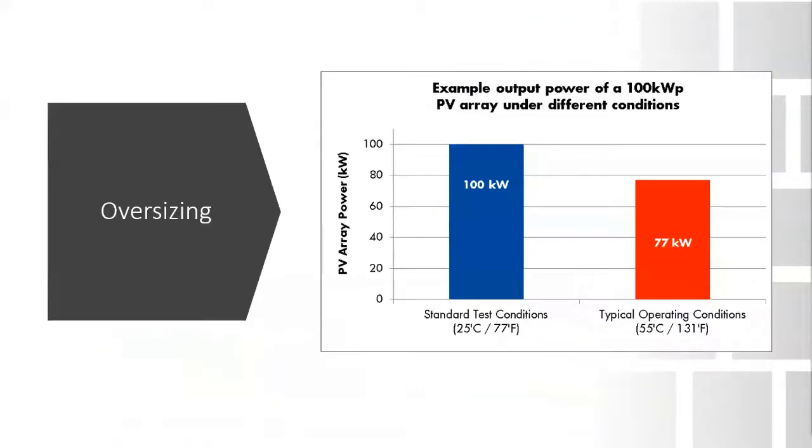When homeowners are putting solar on their home, they're doing it because they want to make a return on that investment primarily. So keeping installation costs down is key. The other thing I want to touch on, because that slide only referenced AC inverted backfed power, I want you to keep in mind there is something known as oversizing. So I can have more DC, so modules on my roof or ground, than I can have AC inverted that's backfed into the utility.